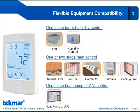The 553 can control up to 2 stages of heat, and those 2 stages of heat can have heat terminals of radiant floor, fan coil, convector, furnace, and backup heat. So unlike the 557 where your first stage of heat is limited to radiant flooring, on the 553 you can actually choose the heat terminals for each stage of heat if you're doing a 2-stage heat application.